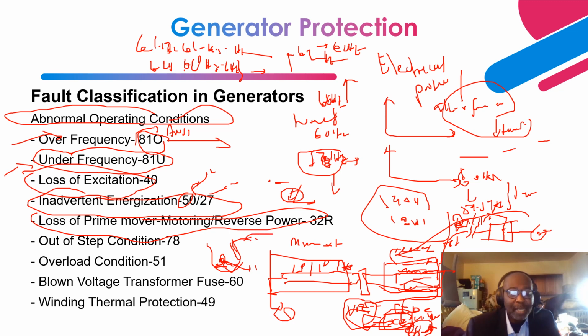Then from there, steam flows through piping that comes into the high pressure section and hits the turbine blades. That's how the shaft of the turbine starts turning to convert into mechanical power. Then it comes to the bottom of the high pressure section of the turbine, and goes back and gets reheated to make it more dry.